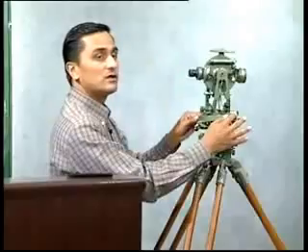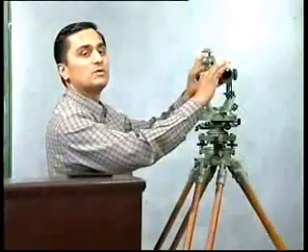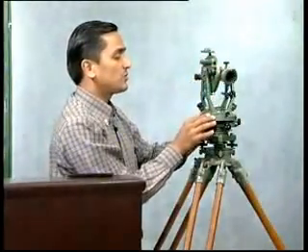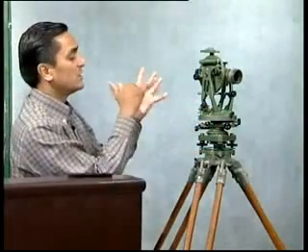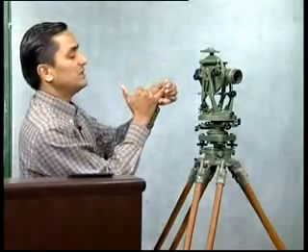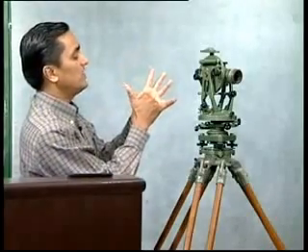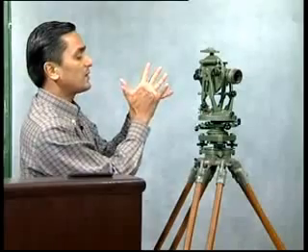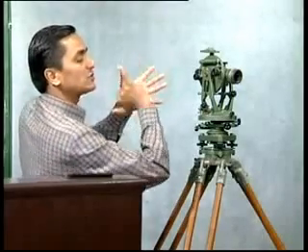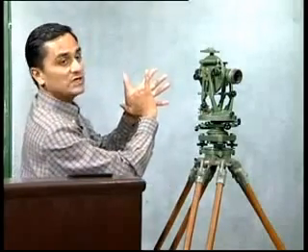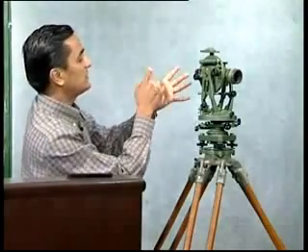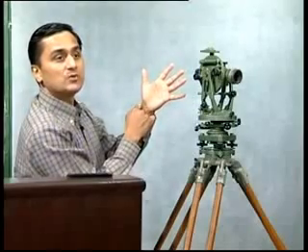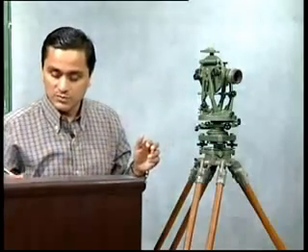Now, when we measure the angle, we rotate our theodolite and we are sighting through this telescope. We will see this telescope in a moment. So we rotate it. So basically what is happening? If for example let's say this is 0 degrees, the reading initially for this vernier and this vernier are 0 and 0. We rotate our telescope, so what happens? Our index rotates. So once this index rotates, the reading against this vernier over here, this angle, and for this vernier, this angle changes. So by rotation of this, we are able to measure the angles.